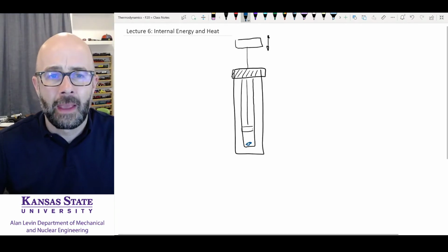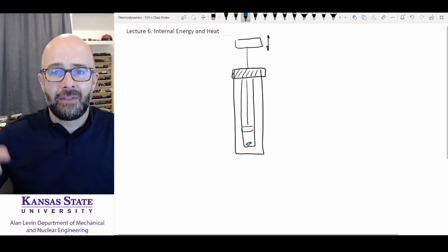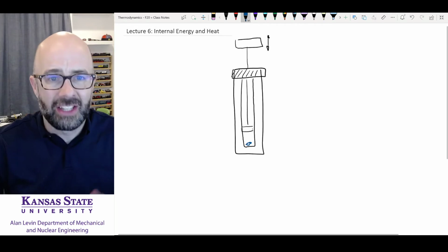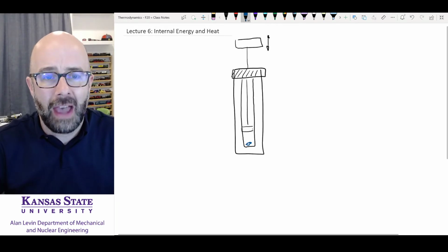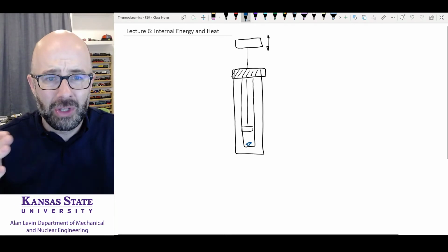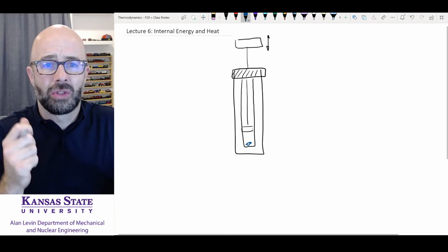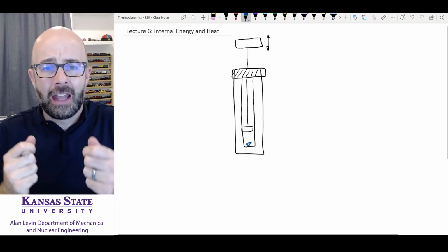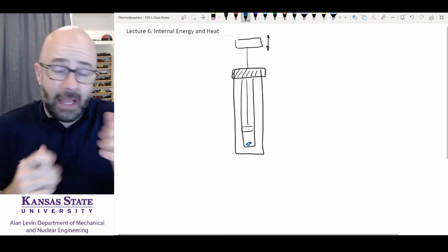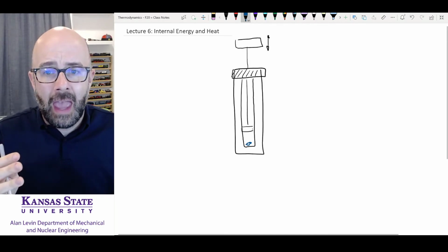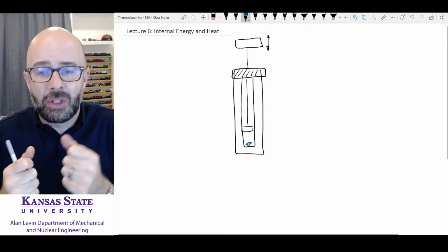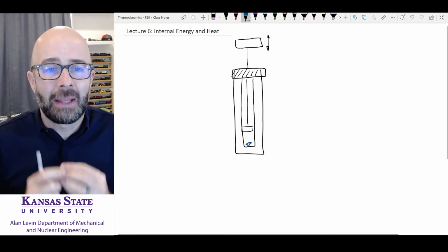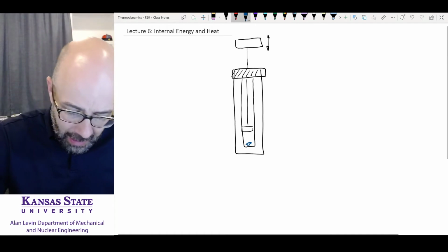And what happens is that if I can rapidly depress that plunger, this air is compressed so fast that the molecules inside of there, just hanging out like this, and then that pressure is increasing, and they start going really, really fast. And that temperature rises. The temperature is the kinetic energy of the particles. The temperature rises, and it causes that flammable cotton to burst into flames. And so we would have flames.